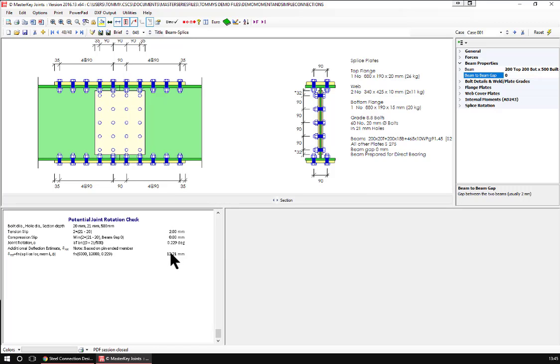So even with the 1 mil close tolerance holes, you are going to get a 12 mil movement vertically down on a 12 meter span. So 1 in 1,000 is that physical movement, which isn't that bad.